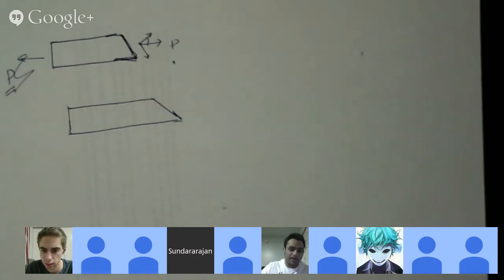The beam is OB. O is supported against the wall, and then there's a rope connecting B to another point on the wall with a mass hanging from it. And it says that the wood beam breaks while shipping, and then the construction worker cuts the beam at an angle of 45 degrees and glues the pieces with an adhesive that can withstand a shear stress of 44 megapascals.